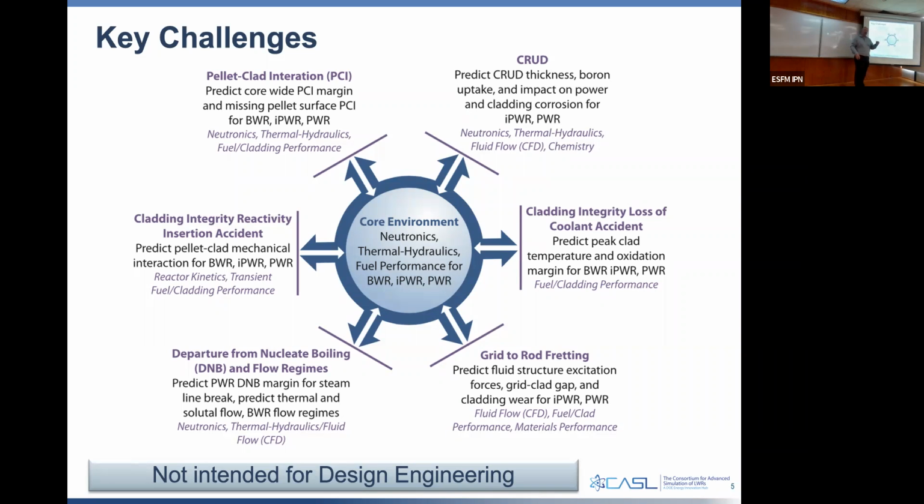And then that control rod, a weld failed on the housing up above it, and that control rod shot out of the reactor. So when you lose that absorber, suddenly you're adding reactivity into the system, and you're getting a huge power spike right there where that control rod was.